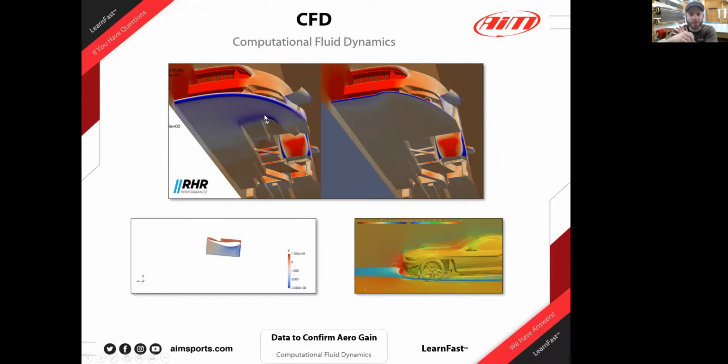The blue across the leading edge of the tunnel. And if you look at them, the whole body of the splitter is a little more blue than the whole body of the one on the right, the flat splitter. So CFD is a hugely beneficial tool. That, coupled with the wind tunnel, because one thing you can't really model in CFD is, like we mentioned earlier, the little gaps around the hood. Exactly how is the air going through the radiator? Is it ducted well? So one is not better than the other. They both are useful for sure.